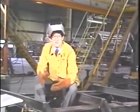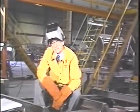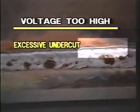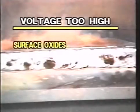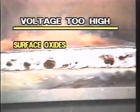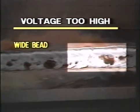In many cases of spatter and poor welds, it's quite often just a matter of a fine adjustment on the power source. Too high a voltage results in a quiet arc sound. The weld will be extremely fluid, producing an uncomfortable amount of heat for the welding operator. Smoke levels will rise as voltage increases. The results of too high an arc voltage are all too obvious. High volts will result in unacceptable undercut. Excessive surface oxides are also usually an indication of too high a voltage.